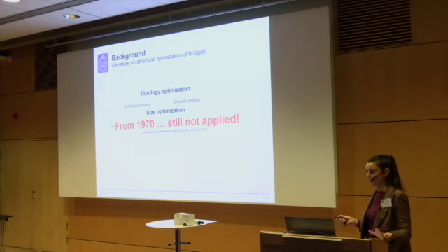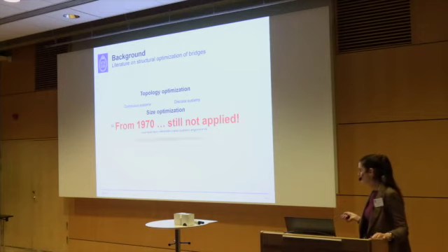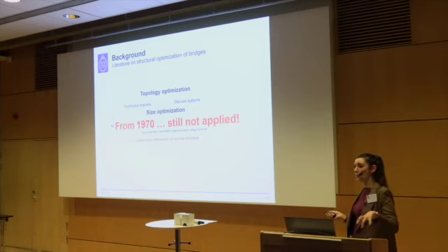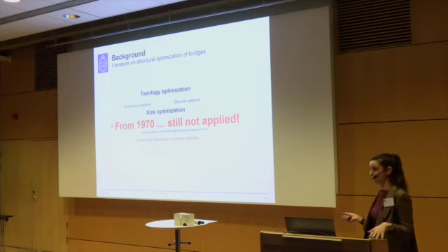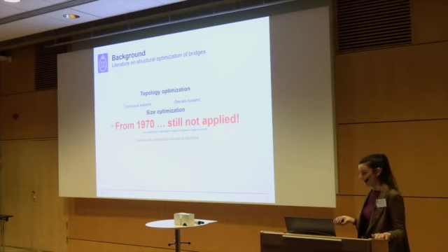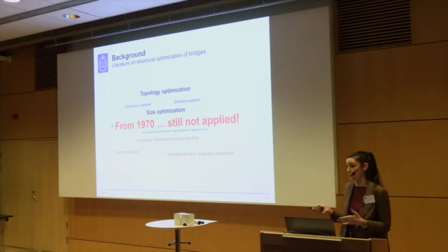There are a lot of reasons for this. Business model is one of them. But if we look at what research did wrong, the main problem that researchers found is that usually optimal solutions tend not to be feasible. They tend to be too complex to be built. The problem there is that most of them focus only on material cost. So they make structures with weird shapes and super slender, impossible to be built. Or they oversimplify the structure, they oversimplify the loads, they oversimplify verification. In the end, what we optimize is no more a bridge.